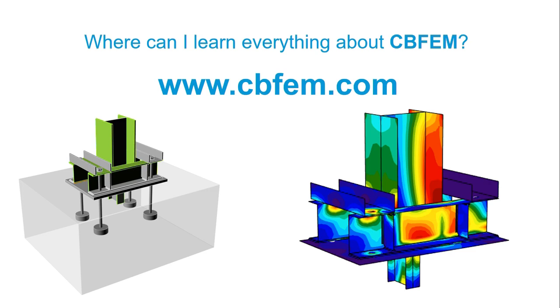Thank you, David. So just to summarize, the CBFEM method will take each part of the connection and model it as its own component, which is also the philosophy behind all design guidelines for structural steel. As this is pretty complicated, it really helps to move what already exists in the code for some simplified cases, with finite elements, to generalize it and make it more robust, so you can apply it for more and more cases. So this has basically almost no limits.